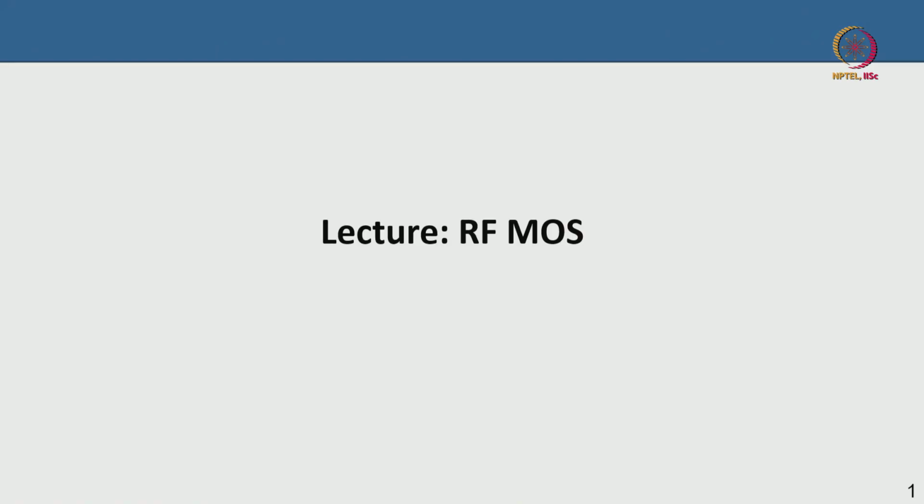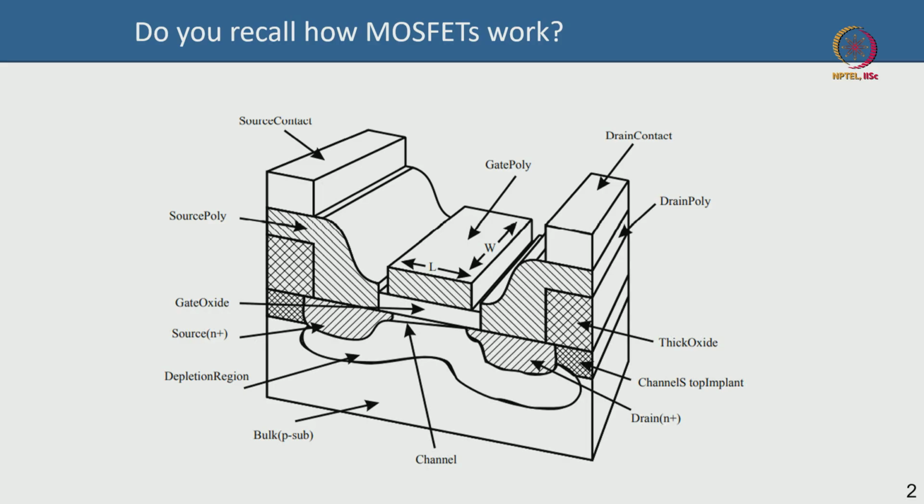Okay, so let me slide over to the whiteboard here. The assumption here is that you are familiar with the basics of the classical silicon MOSFET, the long channel MOSFET, the gradual channel approximation, all the equations and the concepts pertaining to the long channel device operation. So, we shall not go through that. This is the basic schematic of a typical classical silicon MOSFET. You know about the polysilicon gate, the drain contact, the well, the N plus P plus pocket, isolation using local oxidation LOCOS, which was the older generation devices, but this is all assumed to be known to you.